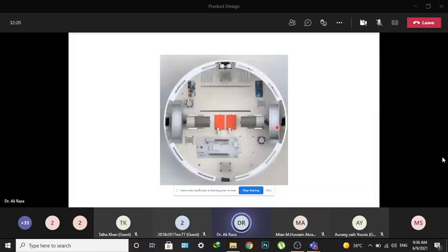And on top of that, these motors need to be driven, so you can see the motor drivers and the controllers over there. The air vents and exhausts are placed there, and then quite a lot of other sensors, and how we are going to place them. You can observe the sonars and the IR sensors. The cliff sensors are also indicated. So quite a lot of discussion went into how the base is designed and how we're going to have all those different capabilities which allow the robot to have movement or navigation inside the apartment.